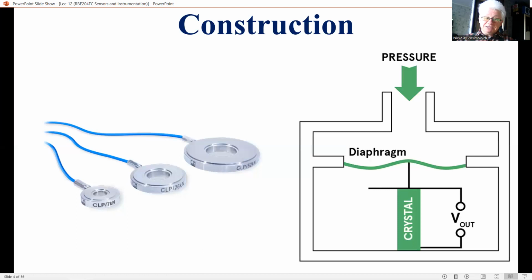A high sensitivity requires a large deformation, which is achieved by a low stiffness of the spring element. Such a large displacement, however, could unintentionally affect the structure in which the force has to be measured. A piezoelectric force sensor, on the other hand, responds directly to an applied force. The associated deformation is in most cases negligibly small, assuring small loading errors in the force measurement.